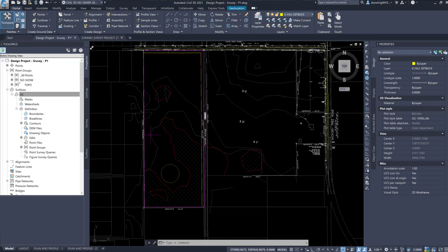So you could put a park area here. You could put some type of amenities. I'll make a list of all the requirements that you'll need, and you'll see those in the assignment portion. All right, so you'll have setbacks that you're going to be required to have. You're going to have widths of lots you're going to be required to develop, right-of-way widths that are going to be required, number of lots that you're going to be required. So those will be in your assignment. But to get started, I'd like to see your all's first ideas of how to lay out a roadway.